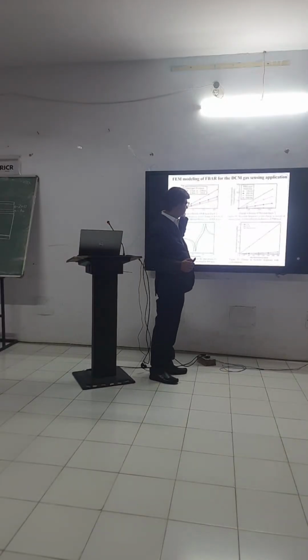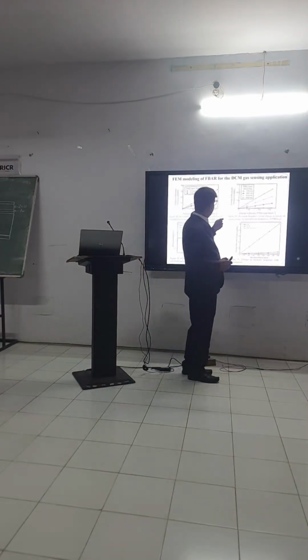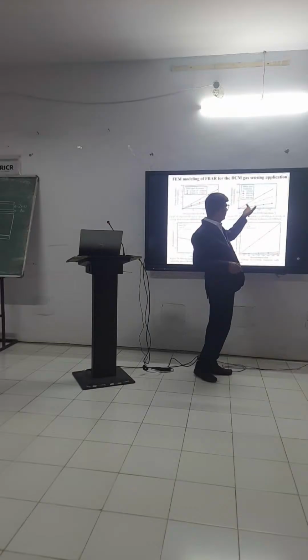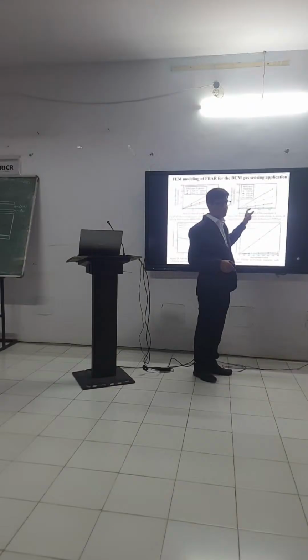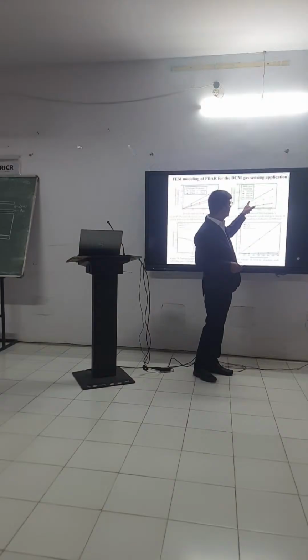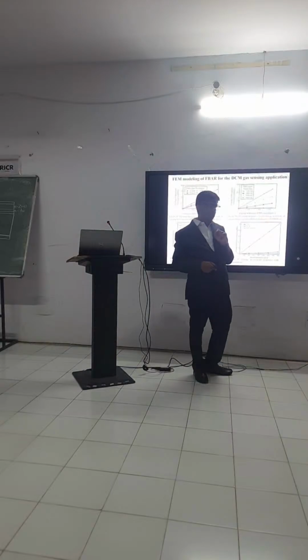Understood? Next, there is a graph that we discussed earlier. You can see here what will happen if you have a different thickness of your sensing layer. But see here, your change in frequency is also increasing with this 680 nanometer. But what is the problem with 680 nanometer? It also has a higher harmonic mode. So that's why we avoid this. We will select 510 as my sensing layer thickness.